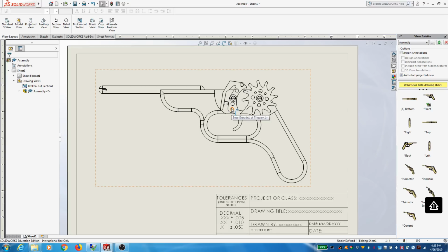One thing, when you have more complicated designs, you may need to expand the number of pages in your drawing packet. So far, our designs have been fairly straightforward, and I've said, please give me an assembly, an exploded assembly, and then each of the parts in order. As the parts in your assemblies get more complex, you may need 3 or 4 assembly drawings to communicate how this thing goes together. And for individual parts that are complicated, like the ratchet and pawl, you may need 2 drawings for that part. So don't be afraid to do that. That was the last thing I wanted to show you, which is this broken out section view. I would like to see something like this included in your drawing packet.